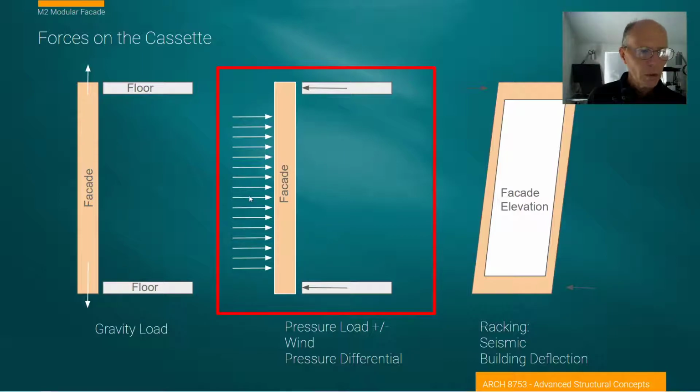But the primary one we're interested in is this idea of what happens to our facade when it's deflected under wind load. I picked this specifically because under certain conditions, this deflection would become an occupant's concern. Obviously, if this was so flimsy as to be a curtain of fabric, its deflection would be quite unnerving in a high rise. And so we want to think about how much it's going to deflect and what the implications of that might be. So we have a uniformly distributed wind load.